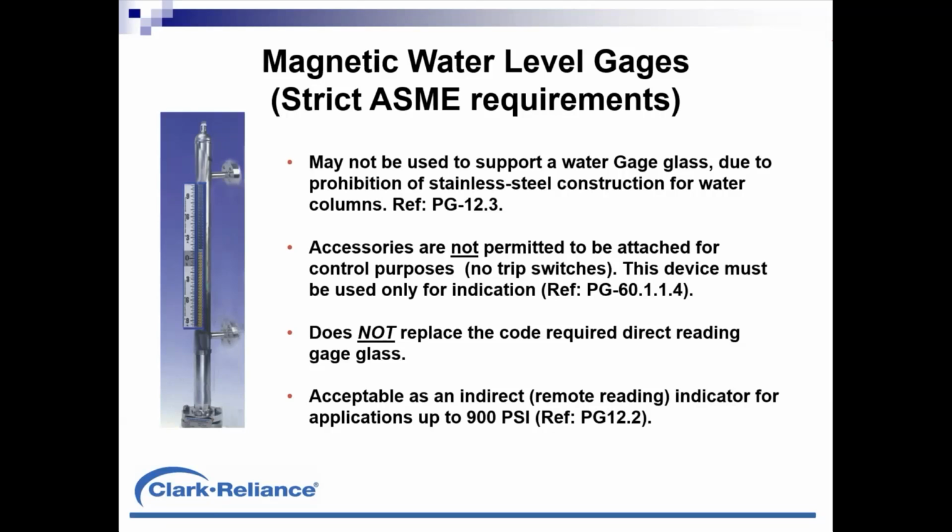For example, if one of these devices were designed to be used at 120 bar, and then someone decides to drop down to say 60 bar in operation mode, it could result in a significant level indication error reading falsely high. So a lot of that risk is mitigated by limiting the pressure of these applications.